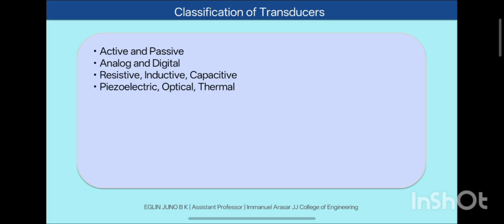For example, strain gauge, LVDT, RTD are examples. Passive transducers generally provide better accuracy and sensitivity, but need additional circuitry. Just think of a device that works even without a battery. That is an example of self-generated energy.